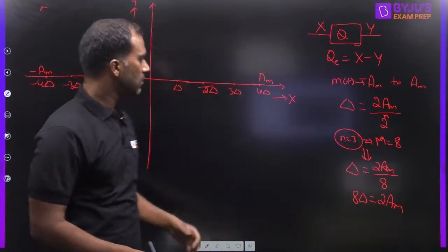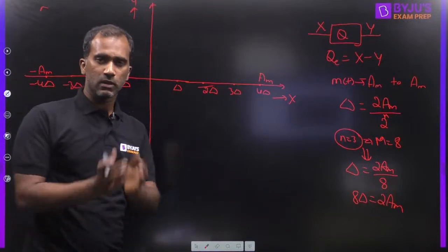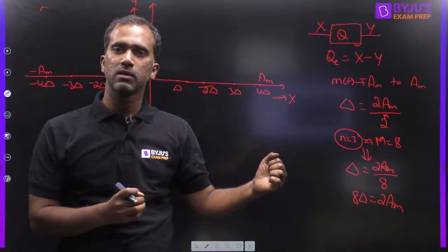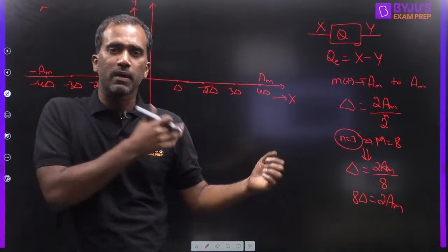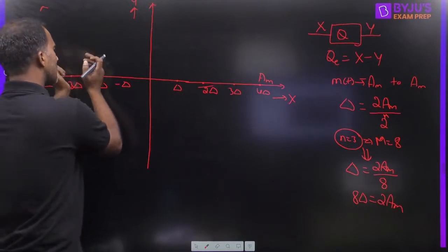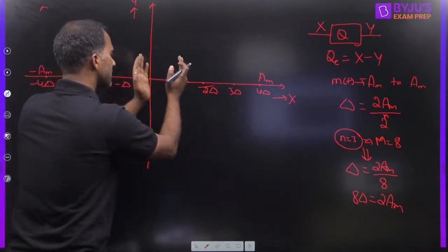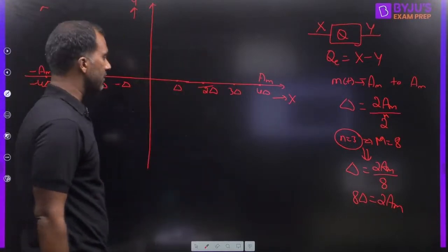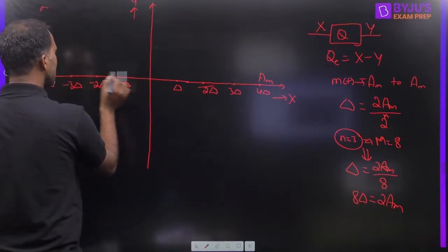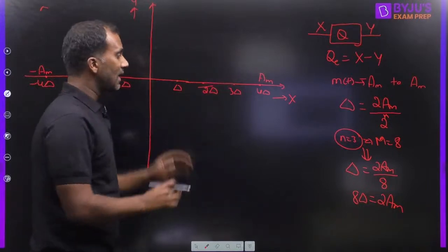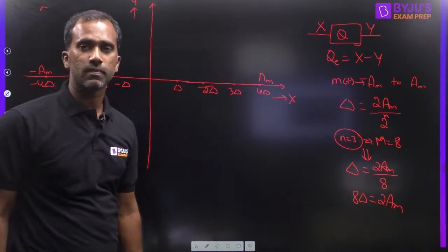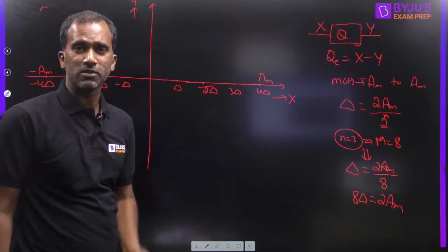Very simple. Whatever voltages are possible for the signal, the total range of voltages, you divide it into m parts. How many quantization levels are there? Those many parts. So we got quantization regions now. This is one quantization region, another, third quantization region, fourth region, fifth region, and so on. Total 8 regions we are having. And whatever points we have selected here, first point, last point and the middle point, all these points we call quantization boundaries. Because they are the boundaries of regions, right?